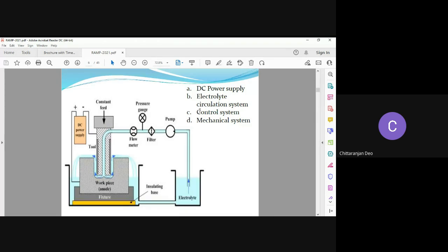One of the most important parameters of electrochemical machining is maintaining the constant voltage level. This is achieved by the control system providing a movement of the tool at a constant speed equal to the linear rate of machining. The process is steady state, performed at a constant gap. Typically, the gap is maintained between 0.1 and 0.4 mm. So this is the main role of this mechanical system.